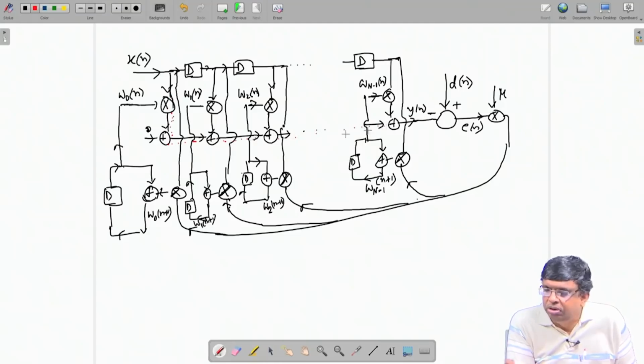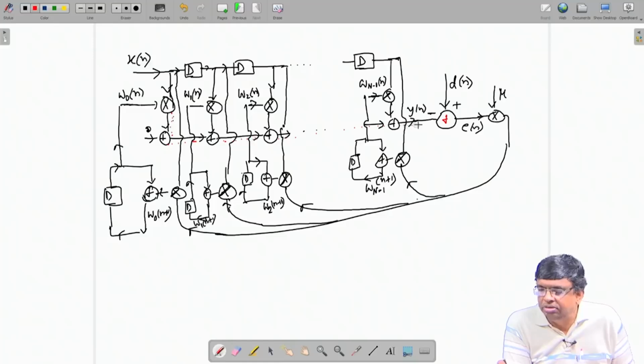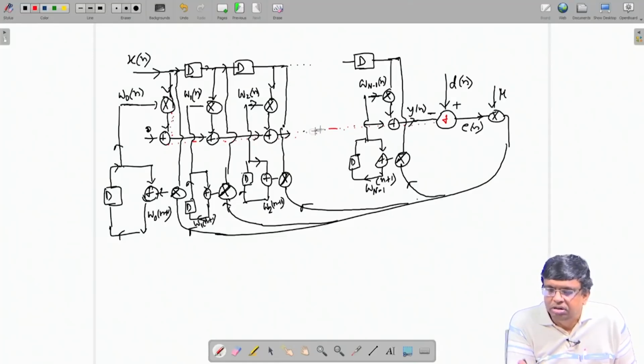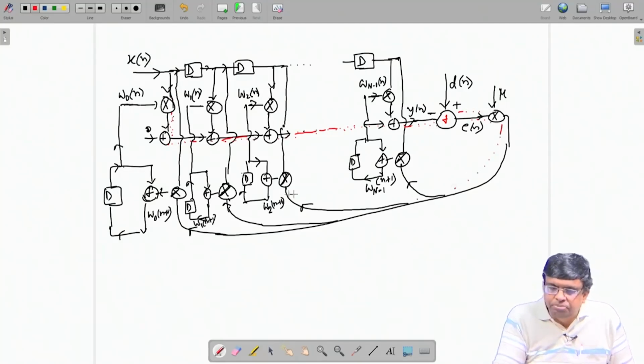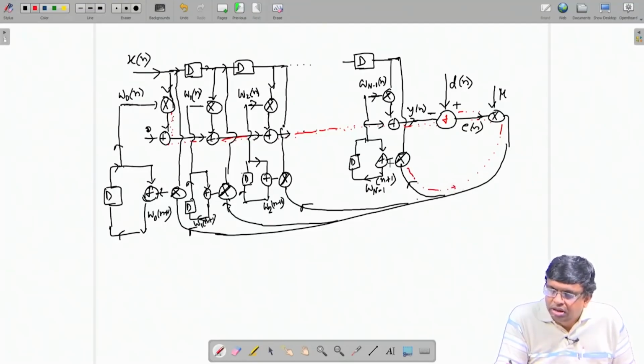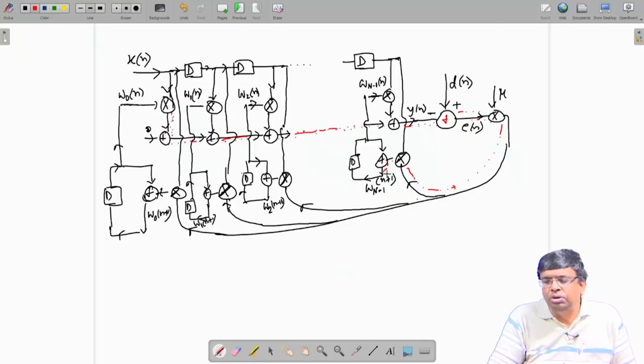So, one multiplier and so many adders, then again this is also an adder subtractor, but this subtraction and addition they are equivalent. So, this is the line, one multiplier, so many adders, then again a multiplier, then these are parallel structures. So, you can go up to either this and then up to this, that is all. Okay. And then there is a delay, or you can try here, they are parallel. So, this is a critical path.